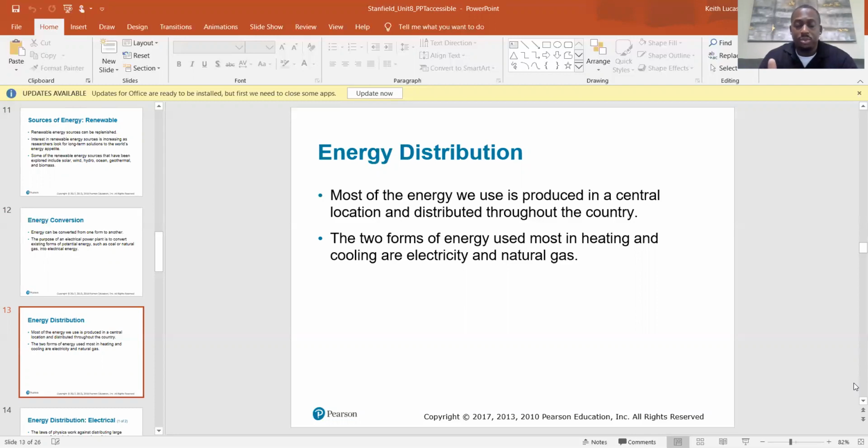You have your heat pumps, which give you your cooling and your heating from the compressor. And then you have what's a little bit more common. I guess it just depends on the application. They're both pretty common, but the other type of systems are called gas electric systems, where you get your cooling from the compressor, but you get your heat from the natural gas furnace. So those are two different ways. When you're dealing with gas electric systems, you're going to have to have a good understanding of thermodynamics and the natural gas furnace, as well as electricity.